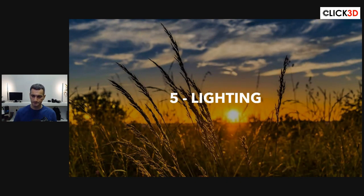But again, the advantage of the laser scanner is that you can always scan and pick up geometry data, regardless of the lighting situation. On older scanners, depending on the wavelength that was emitted, if it was really sunny outside, then it would cause a problem. Some scanners that use wavelengths of light in the 800 or 900 nanometer range are going to be fighting with the sun outside. So in very bright conditions, your range will drop off with those types of sensors, whether it's a structured light scanner or a LiDAR scanner or whatever. However, most laser scanners nowadays will use a wavelength of about 1550 nanometers. That's a very, very specific wavelength.